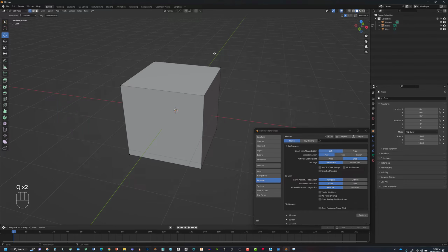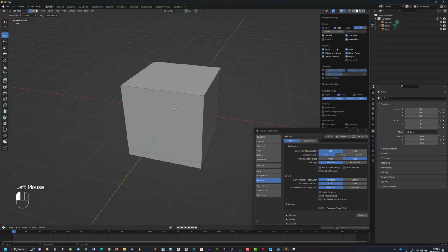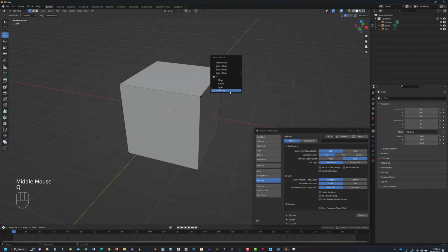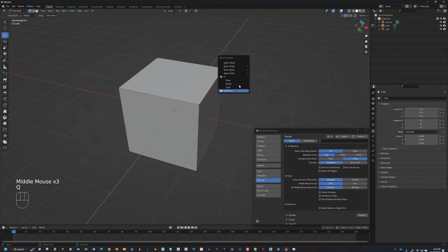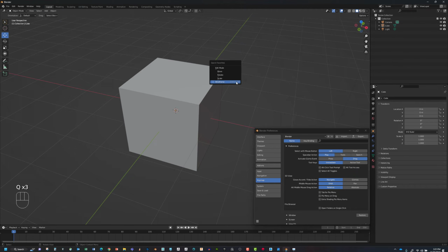And if I go into edit mode, let's see if that still works on here. I might have to do it just for edit mode. Like I was saying, quick favorites work with the different modes that you're in. So let's go ahead and click here, and then you can see it looks a bit different at that point for this. I'm going to right click and say add to quick favorites, and then now I've got the ability to turn on or off wireframe. Well, actually it's not going to turn that off in this mode because it's going to let you see the verts, the edges, and everything. So if I go back to object mode and then just turn the wireframe off, I can do that.